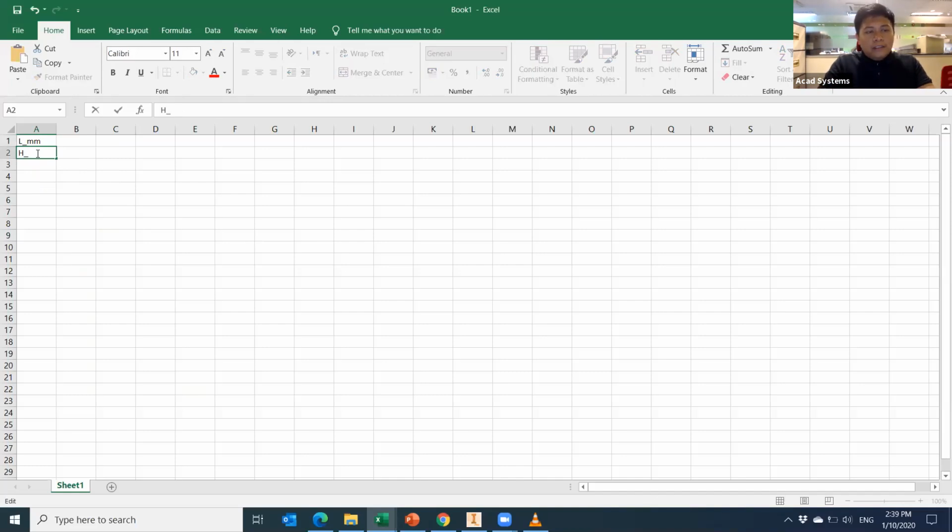So normally I will practice like this, H_mm or H1_mm. Then you just need to key in your value, for example, 70, 50, 40, and then at C1 you can put your unit, mm. If I plan to have one parameter which includes an angle, I can click angle, specify the angle, and put DEG for degree. So that will be the starting point for parametric modeling.